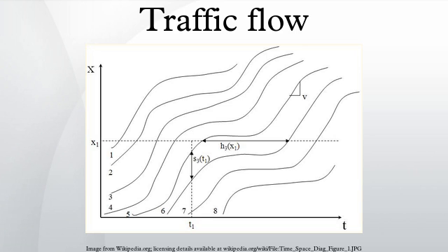Suppose that, at time t, the truck slows from free flow to V. A queue builds behind the truck, represented by state U. Within the region of state U, vehicles drive slower as indicated by the sample trajectory. Because state U limits to a smaller flow than state A, the queue will back up behind the truck and eventually crowd out the entire highway. If state U had the higher flow, there would still be a growing queue. However, it would not back up because the slope S would be positive.